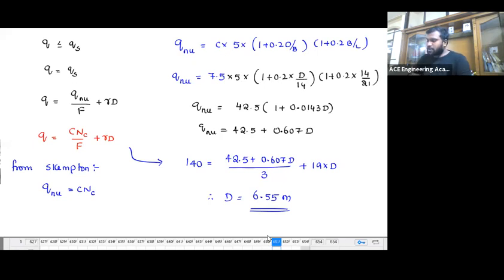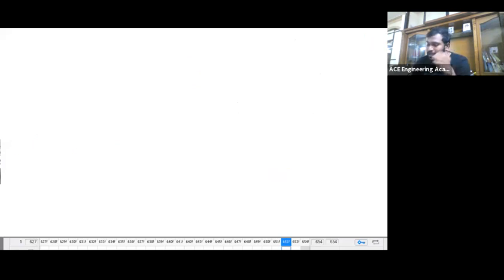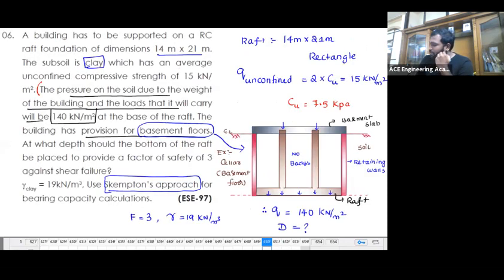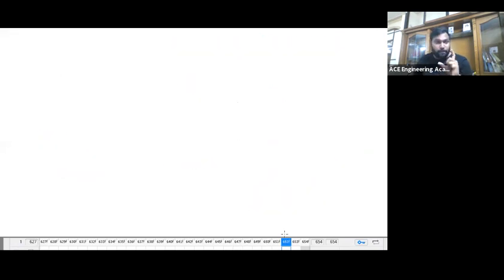So now let's come to the bearing capacity. We discussed the analytical or numerical analysis by means of Terzaghi's theory, Meyerhof's theory, and all those things. Now, in order to determine the ultimate bearing capacity, or ultimate load carrying capacity, we are going to do a test known as the plate load test.